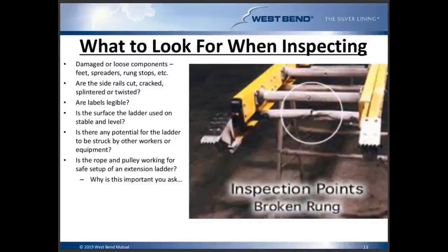Other things to look at when you're doing your inspections of the ladders are damaged or loose parts. So the feet, right? The base of support is what's holding that ladder in place. If those feet are damaged in any way, if bolts are loose and nuts are missing, there's a potential for that foot to become dislodged or the movement to throw the worker off balance. So that would be a good starting point when doing your ladder inspections, to make sure those feet are in good condition.